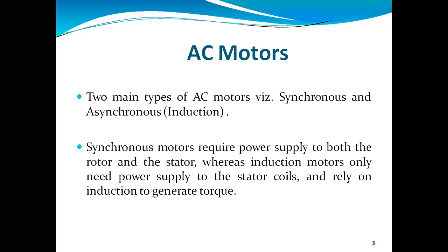But one type of AC motor, the asynchronous AC motor, or asynchronous induction motor, will not require power supply to both. It means only the induction motor requires power supply to the stator, and it depends on induction to generate the torque. Here the rotor part will not require the power supply.